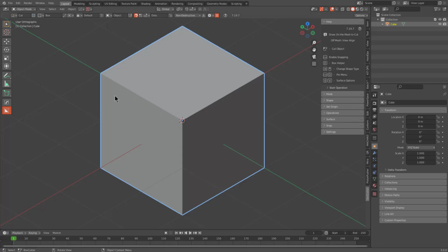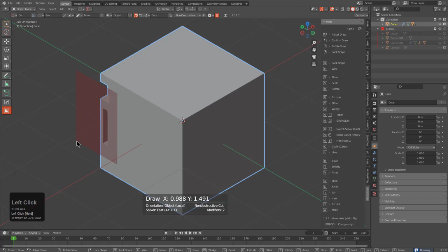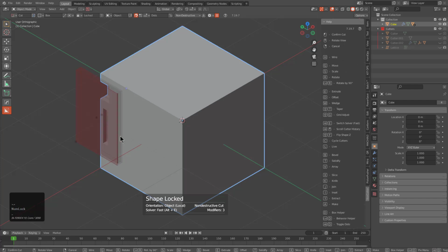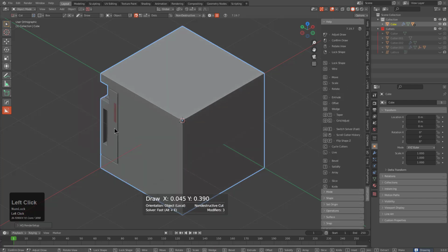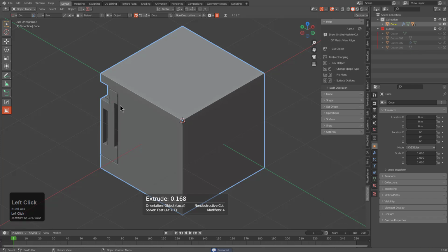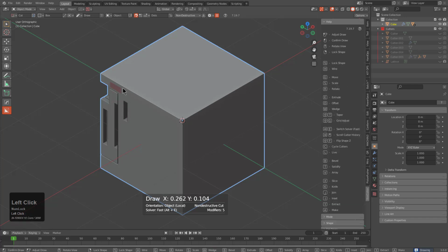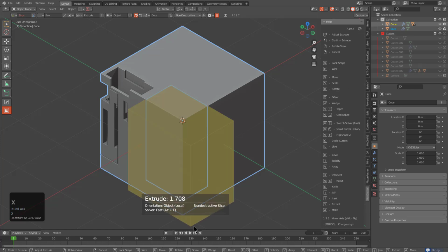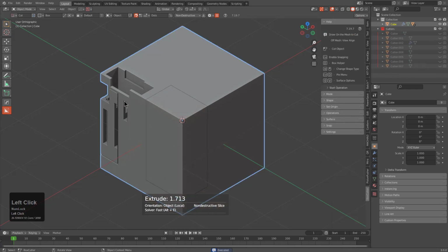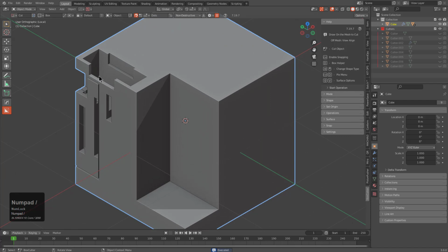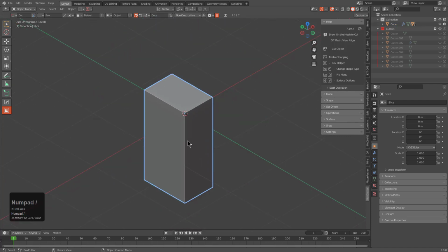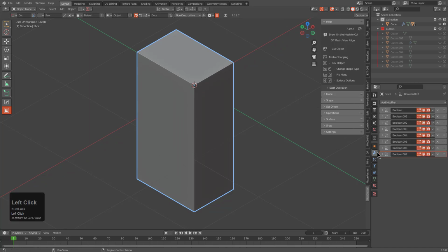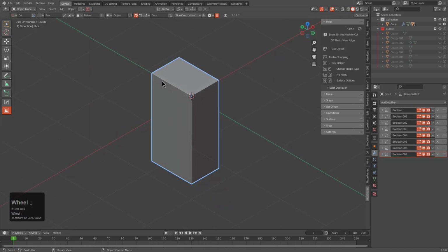Now that we've reviewed what Boxcutter Smart Apply is about, let's attempt to cut some cuts on the left side of this box, pressing T to solidify, maybe adjusting the viewport to be a little bit more visible. We're just cutting in some random cuts on the left side of our box. From here, I am just going to perform a slice operation on the opposite side. So this object, as we can see, is the main object, and this object is just a slice of the secondary object.